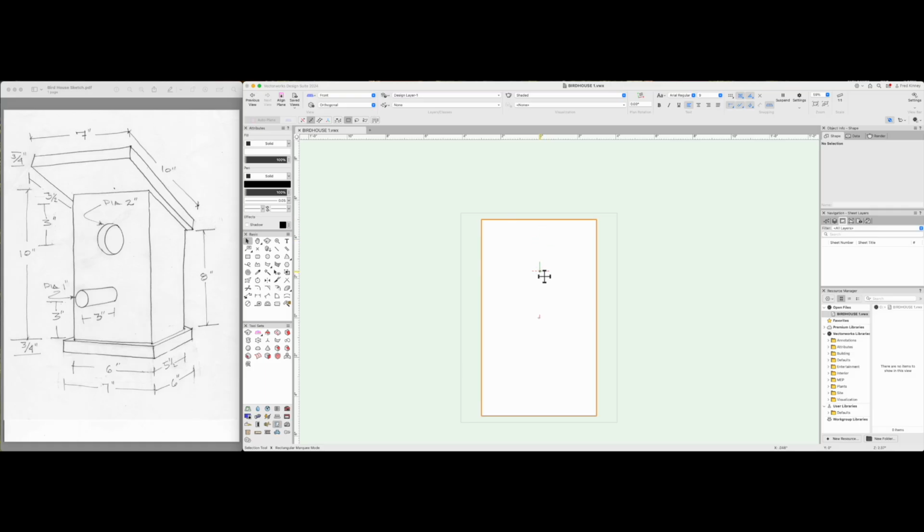And there's many different ways to do it. One option is to draw a line. The 2 in the top bar, not the 10 key, creates a line. So you draw a line, pull it down, and you start to go in the direction you want. Okay? In this case, we're going to go straight down. If we come down, it will know where we intend to go.